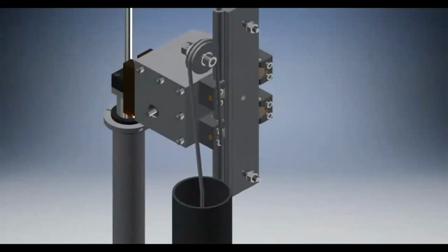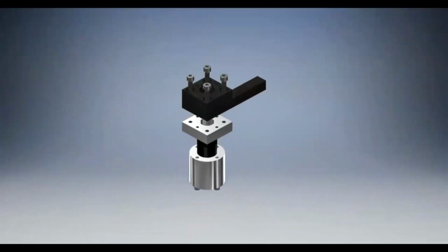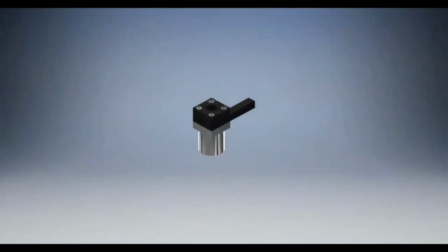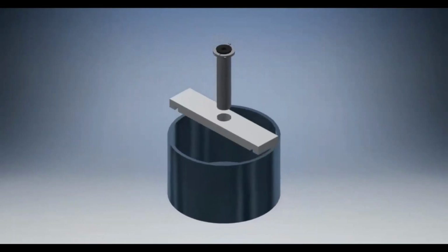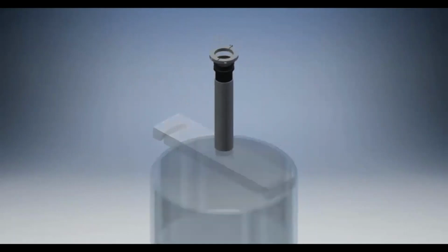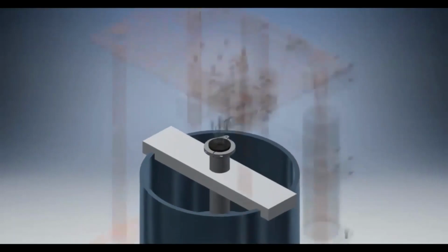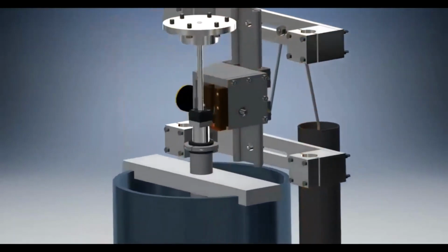And this whole setup will move together when the pile is penetrated to make sure we always have a constant hammering distance. And this is the anvil. And on top of the pile, we also have some special design part which can help us to have a laser system to basically measure against this thing and tell us how much we really penetrate the pile in. And this is basically the idea of this whole setup.